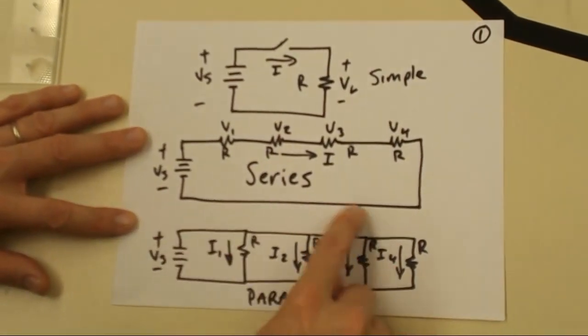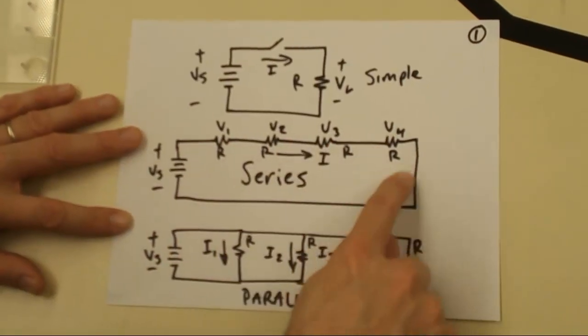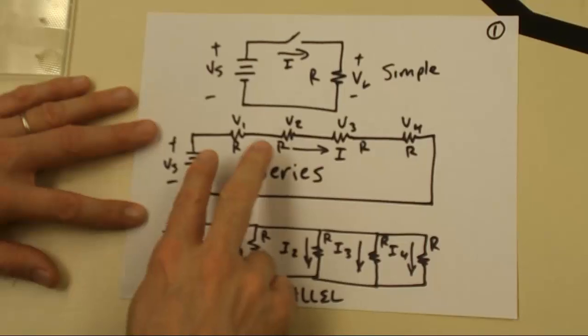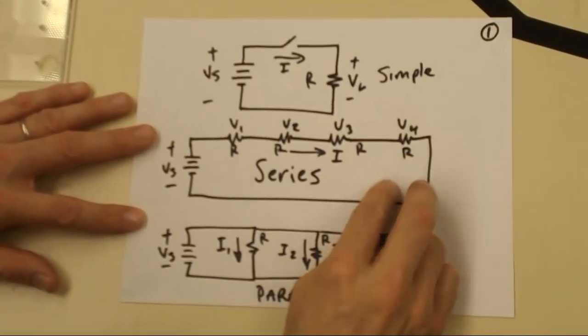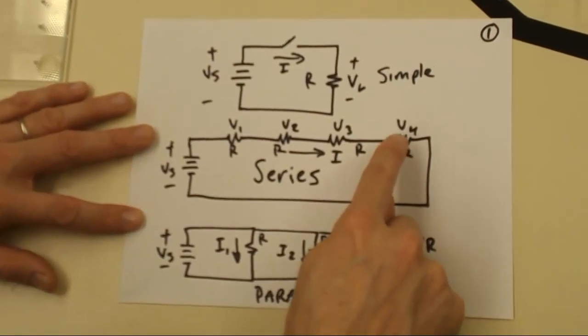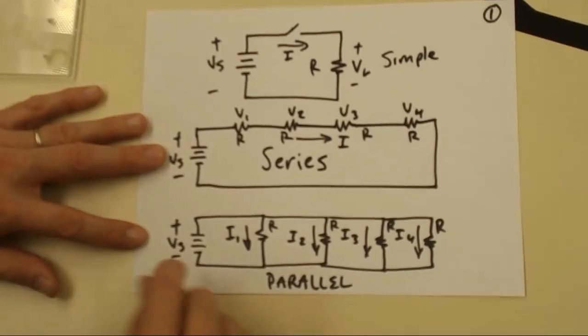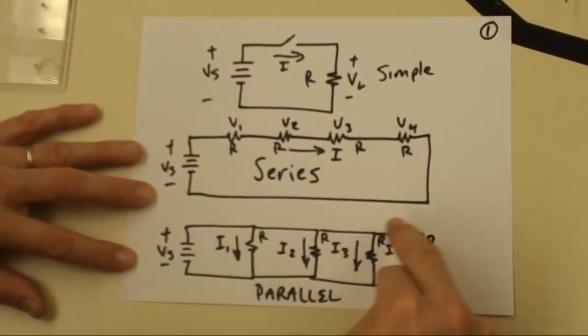So the series activity you did last week was four series resistors, which of course had a common current passing through all of them, so the current measurement was very similar. But they did have separate voltages. Because the resistors were all the same, Ohm's law helps us figure out that the voltages should have been very nearly the same.